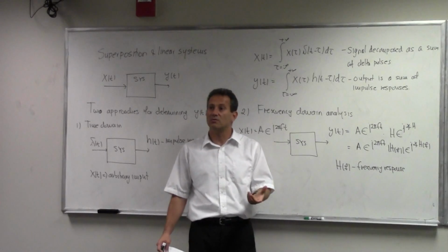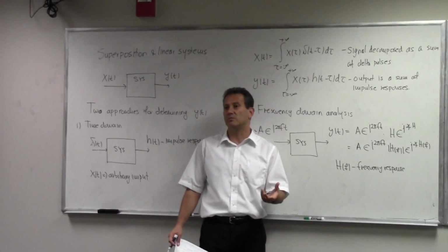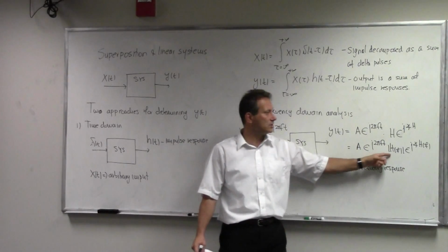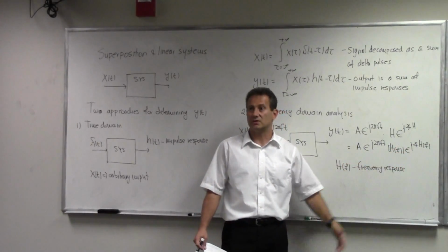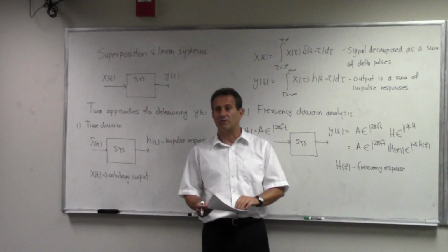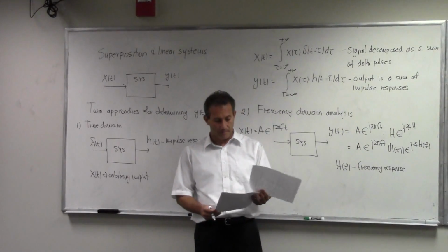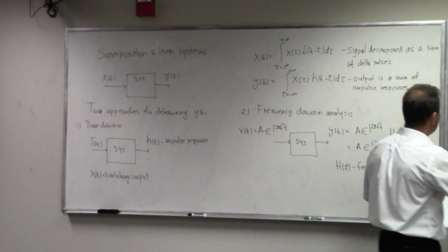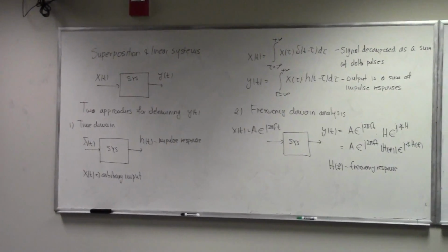Then what I do is what is called a frequency sweep. You change your frequencies and you get a pair of points for every given frequency. This way you generate what is referred to as the frequency response of a system, right? Now, that means in a lot of circumstances, this is how we're going to analyze our system.